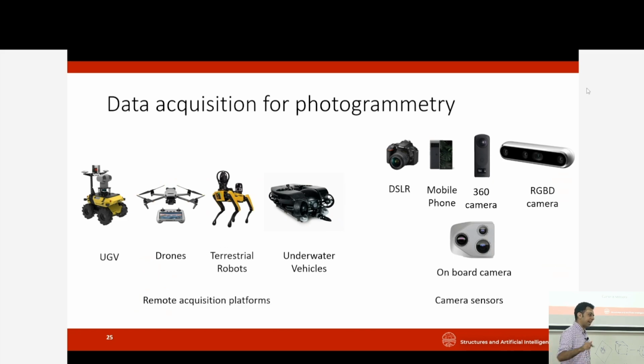Now, if you have very accurate camera positions, say because you have a very accurate RTK GPS, then you can get away with not using the ground control points, relying on that GPS data. But again, even modern RTK GPS systems are not going to be as accurate as having really good ground control points from traditional surveying. Okay. So there's synergies between these approaches. It comes down to what you're looking for, right? How accurate do you need the model to be?